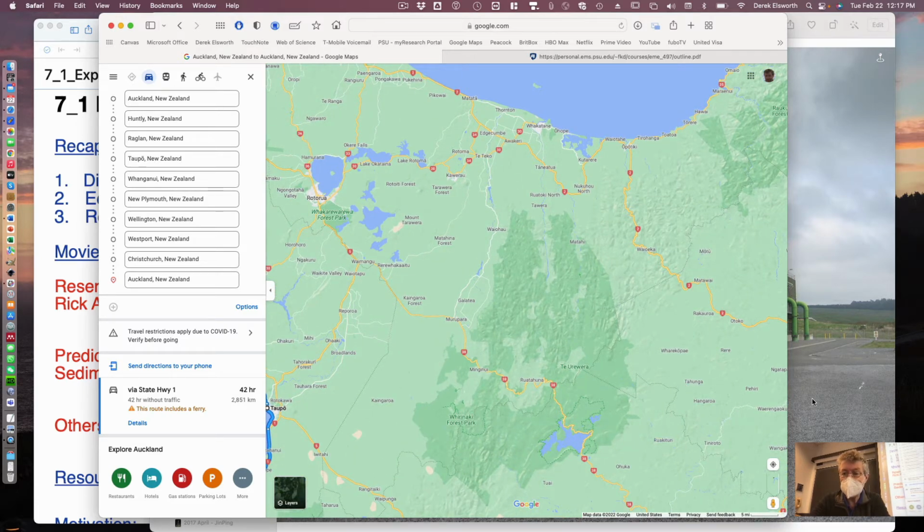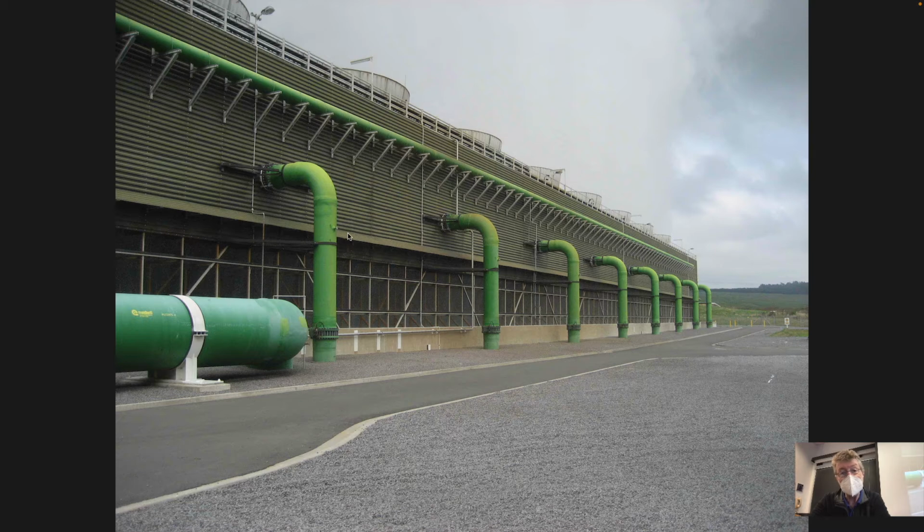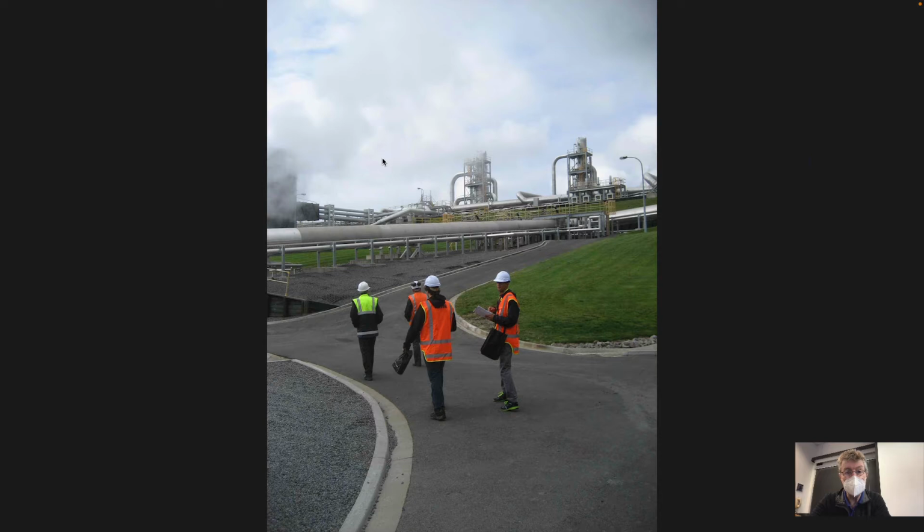But in this volcanic zone, this is one of the geothermal fields. This is Rotokawa, I think. This is a cooling tower, so this is a condenser. Cool air being driven through these fans, which are in these cowls here. Water being supplied to them inside a radiator, so that this cooling is able to condense the water and allow it to be ultimately re-injected.